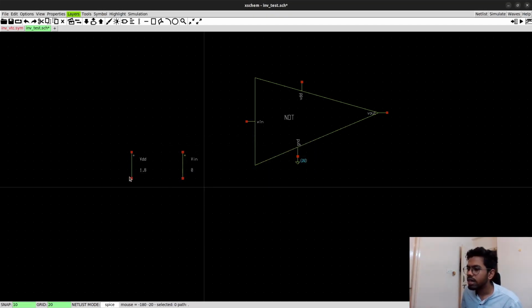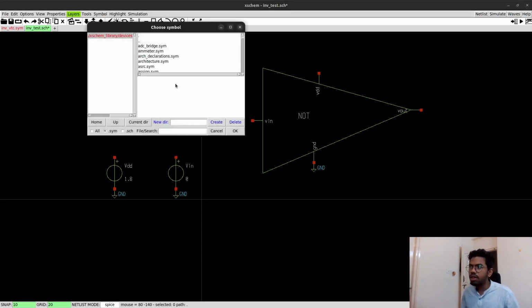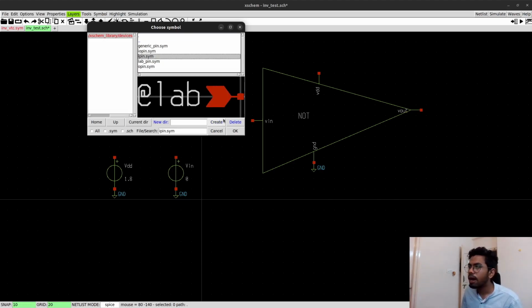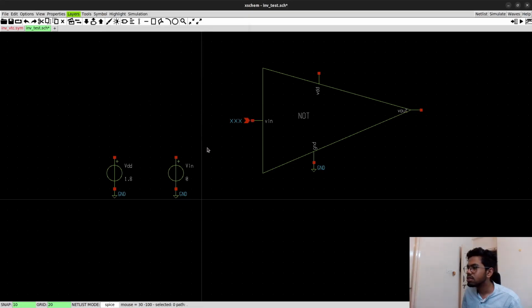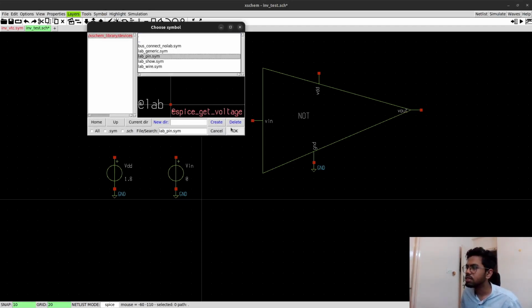And after that I need another ground, another 2 grounds actually. Let me copy it here and here, and let me press Shift I to get the pin. Okay, so this is one pin, and here actually we can give labels also, because we are not creating any symbols. So let me give the labels here. Left, and you can give any one of them, no issue. Left pins.